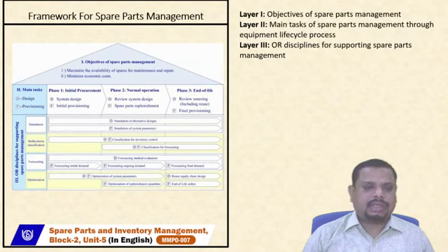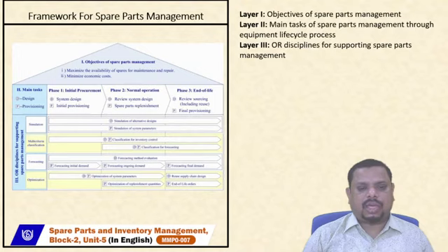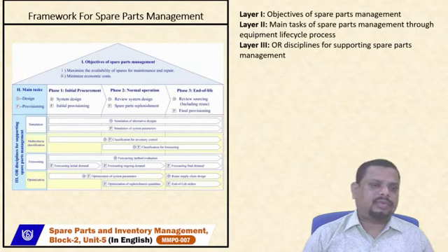Demand forecasting is essential whenever you go for spare parts management because most breakdowns are unpredictable. That is why they conduct qualitative forecasting as well as quantitative forecasting. In most cases, to maintain the spare parts, they focus on quantitative forecasting.